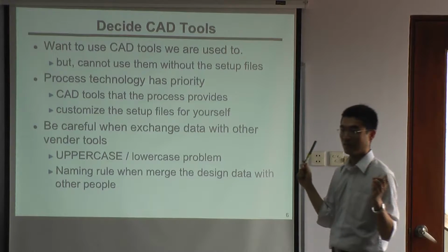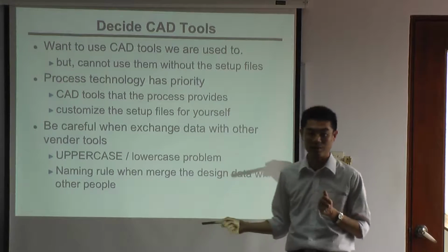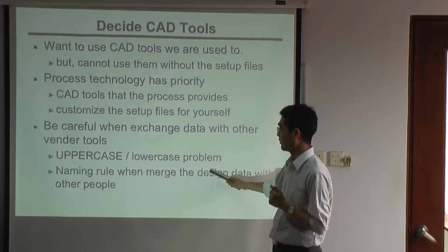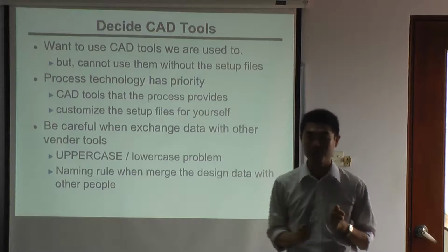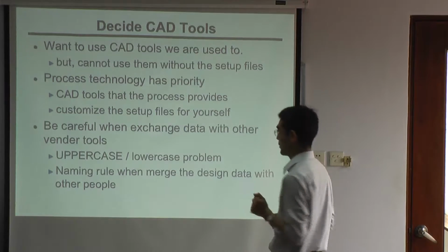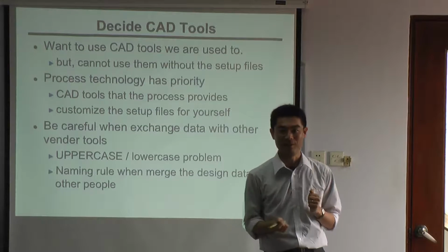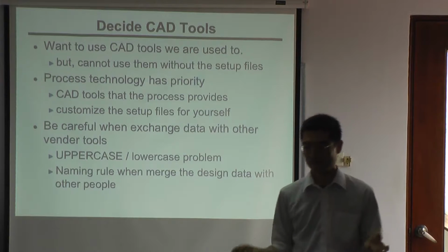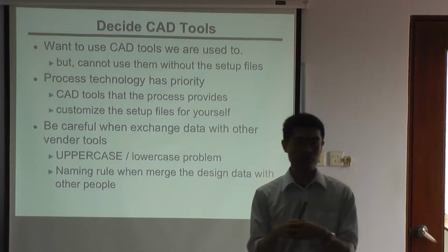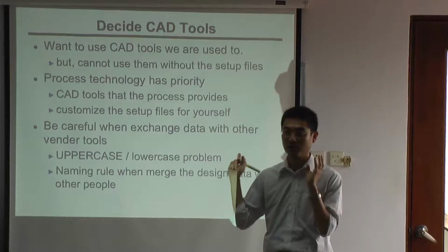So you have to decide it before starting your design. And at this design merge step, you will have very big trouble. Especially this uppercase and lowercase confusion is a nightmare. And once you have mistakes when merged, your chip does not operate. And it is a million-dollar risk.